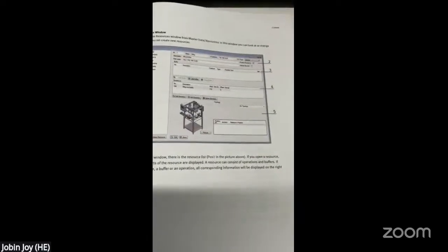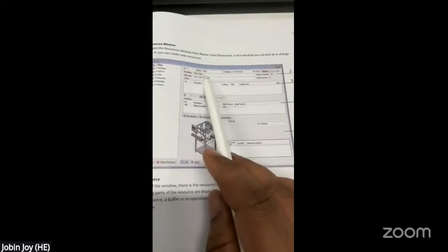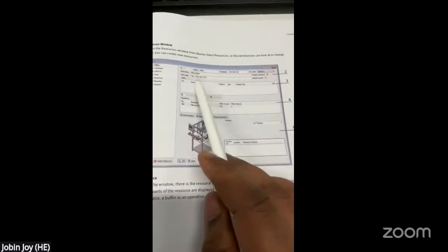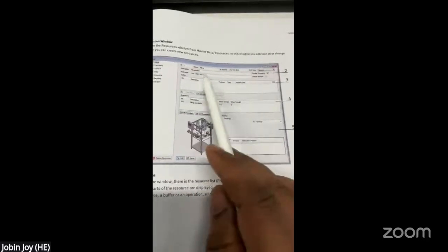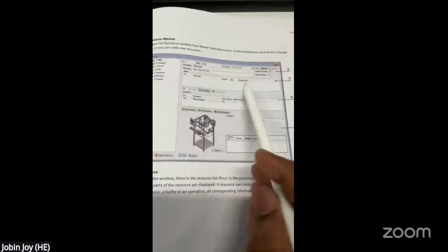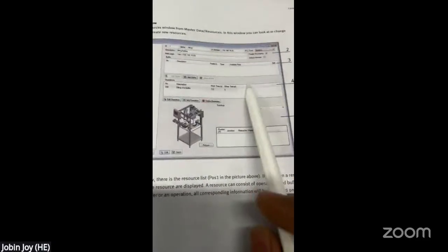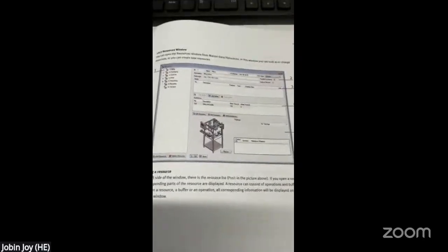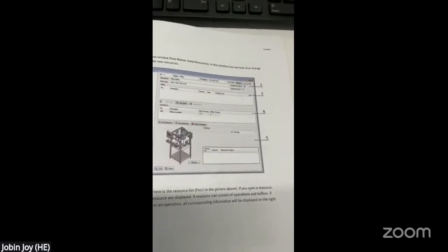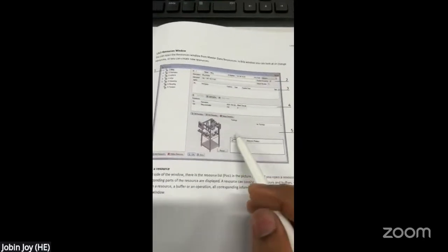When you select the resource, you should give the relevant information. For example, the resource number, the name, IP address, its description, PLC type, which PLC type is being used, parallel processing, default browser, web page link, buffer information. Every resource has a buffer, so we should include the buffer information: buffer number, description, position, type, possible parts, belt number, buffer type such as stack, storage, FIFO to AGV, from AGV, and to and from AGV.